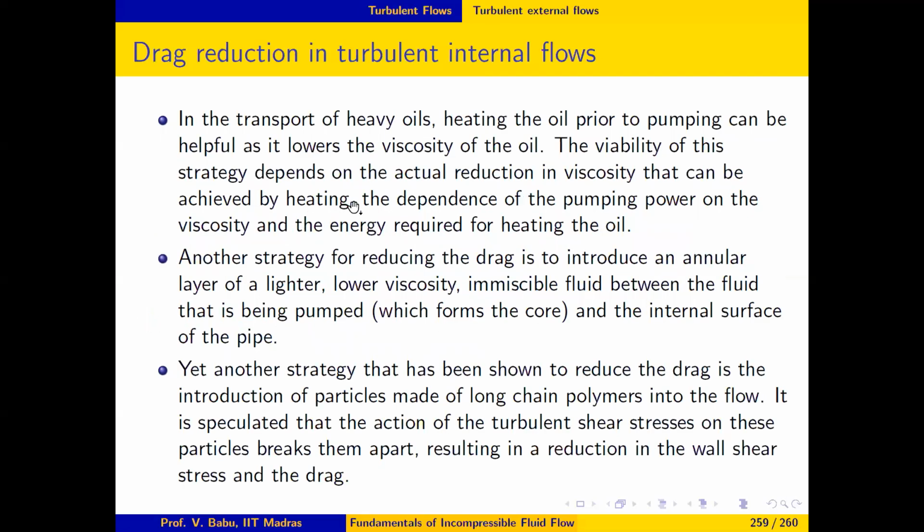Now, we turn to drag reduction in turbulent internal flows. And here are some of the applications where some techniques have been used in the past. For example, in the transport of heavy oils, heating the oil prior to pumping actually can be helpful because it lowers the viscosity of the oil.